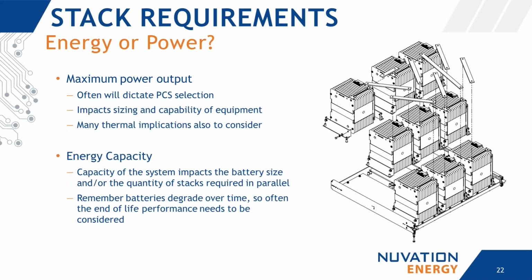Understanding the power requirements often will dictate the PCS selection and in turn typically impacts the voltage range of the battery stack. It also impacts sizing and capability of the other equipment in the system. As well, there are many thermal implications to consider based on the power ratings.